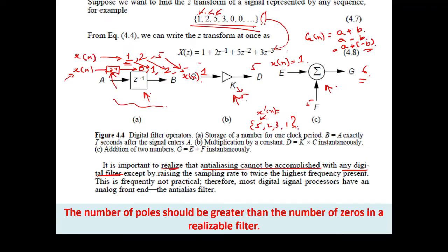While you are digitizing the signal, if any aliasing is present, we will not be able to remove the aliasing from the signal. That means the signal is already corrupted, and we cannot take care of an already corrupted signal. So what do we have to do?